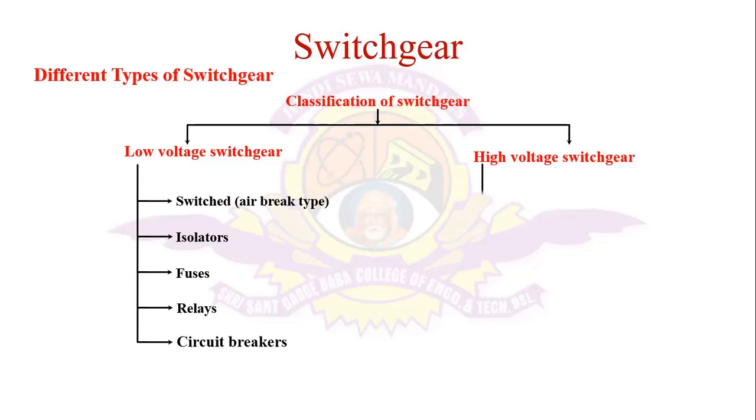Six types of major devices are used in case of high voltages. The first is the oil switches. These are switches whose contacts are immersed in oil for providing better isolation within the minimum time. Next are again the isolators, which were already discussed in case of the LV switchgears. Then next are the circuit breakers, which also come in the category of low voltage switchgears.